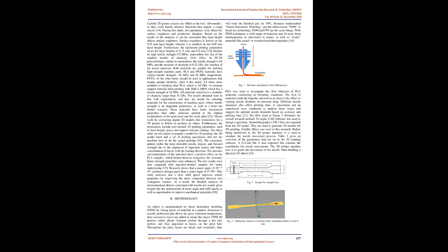It is very important to choose the optimum nozzle diameter, not only to maximize accuracy but also to reduce the extrusion time. Using open-source 3D printing developed for research purposes, it was determined that using an open-source 3D printer with a diameter of 0.3 mm was the best range for extruding PLA material. Typical desktop 3D printers have 0.4 mm nozzles. The nozzles are likely to be brass.